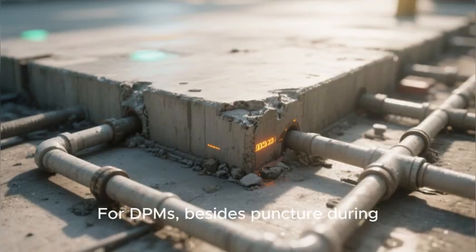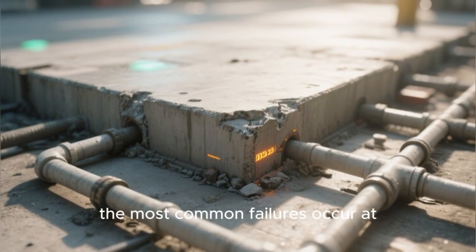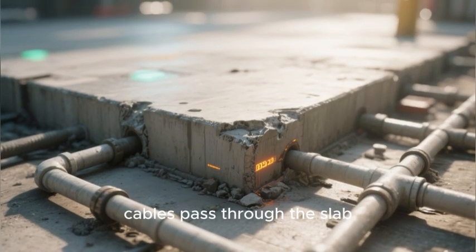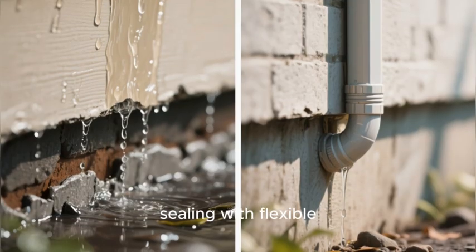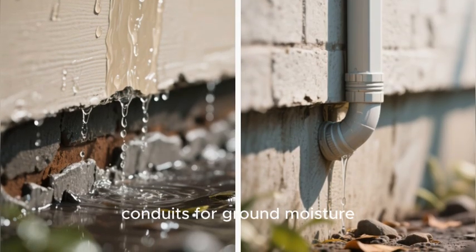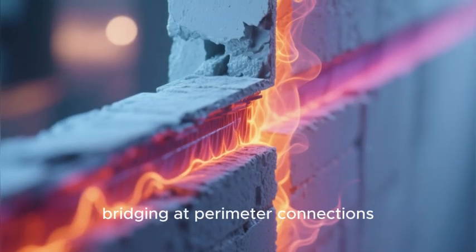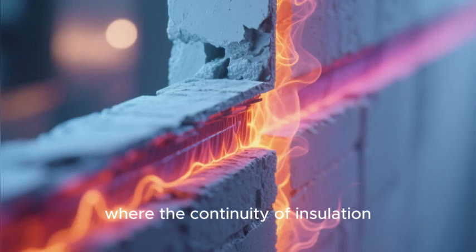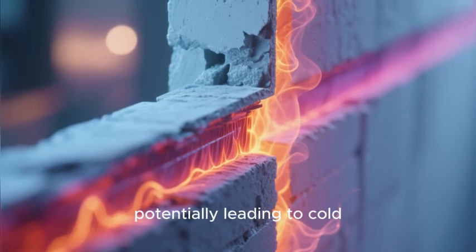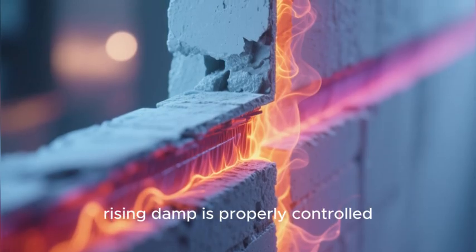For DPMs, besides puncture during concrete placement, the most common failures occur at surface penetrations where pipes and cables pass through the slab. Without proper sleeving and sealing with flexible, non-hardening sealants, these penetrations become direct conduits for ground moisture. Another significant challenge is thermal bridging at perimeter connections, where the continuity of insulation is broken at the DPM/DPC junction, potentially leading to cold spots and condensation issues even when rising damp is properly controlled.